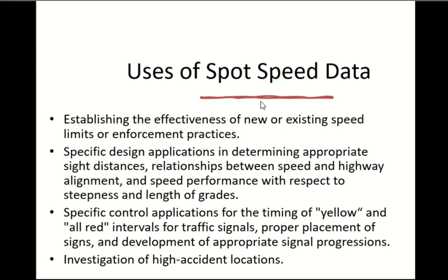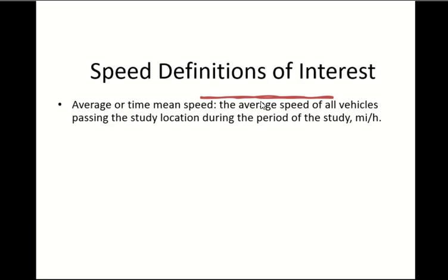Because of the close link between speed and safety, if you find a problem with traffic accidents, then a speed study should be part of your analysis, part of your investigation. Clear? So in all these cases, we do or we can do spot speed studies.